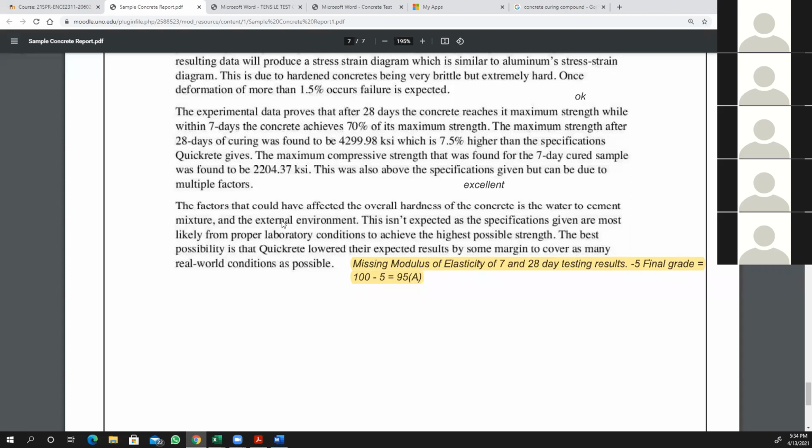If we don't, you get horrible results, not the one that you expect. Even if you reach, let's say, more than 4,000 psi compressive strength, you might have shrinkage in your concrete. You might see cracks in your concrete, and cracks are the biggest problem in concrete.